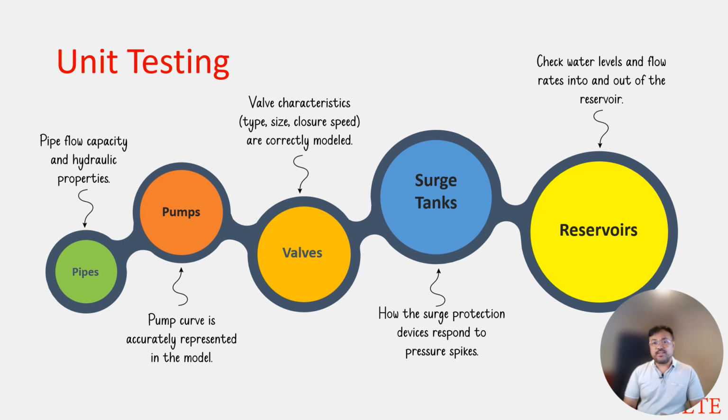For the pumps, we test them to ensure they operate efficiently under normal conditions and respond appropriately to shutdowns and other transient events. We'll also verify the pump's protection systems, such as check valves or surge tanks, function as intended.